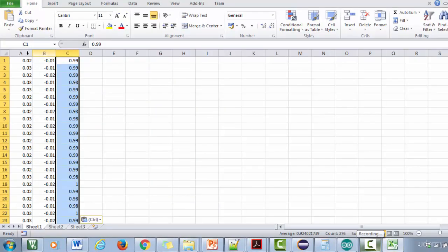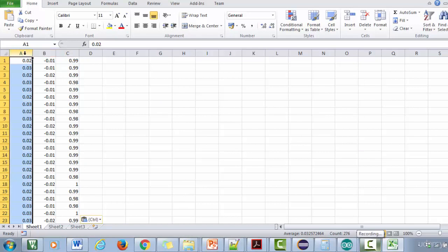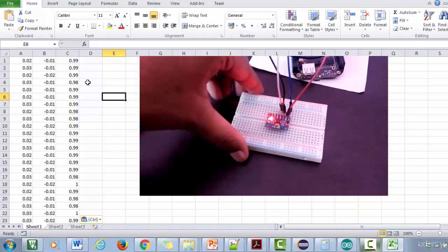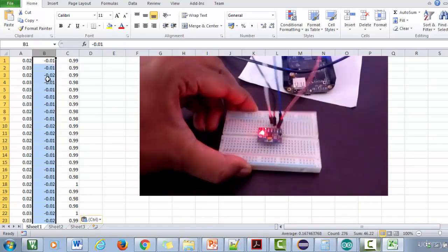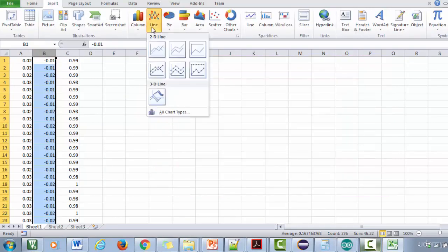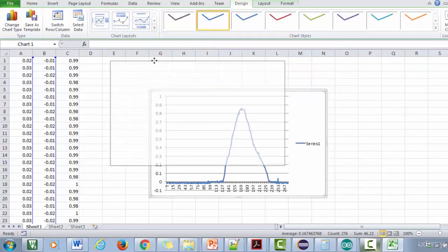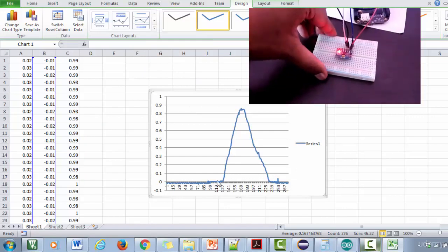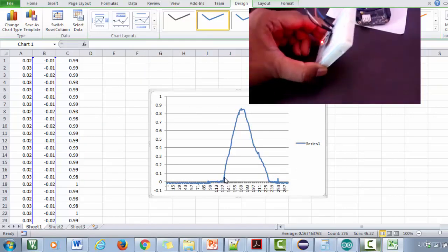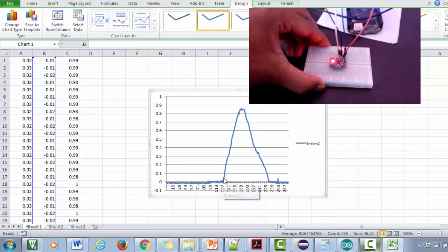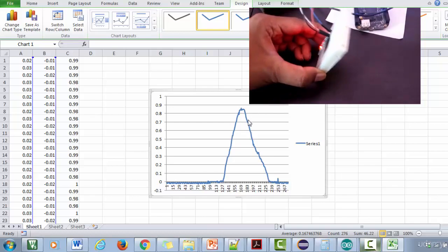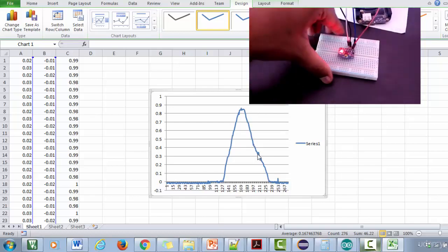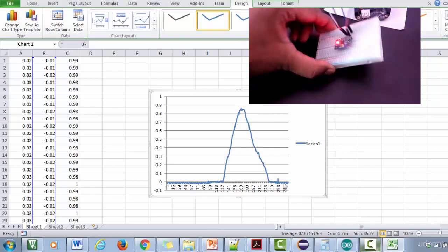Hey, welcome back. So I just copied all these 3 values. So we actually tilted our board on the positive Y direction, like this. So let's plot this Y axis. I'll just select that and go for the graph, and here you can see the Y was 0, then I slowly tilted my board, that means the angle to the surface increased and it reached till here, and then I decreased the angle to come back to the rest position.